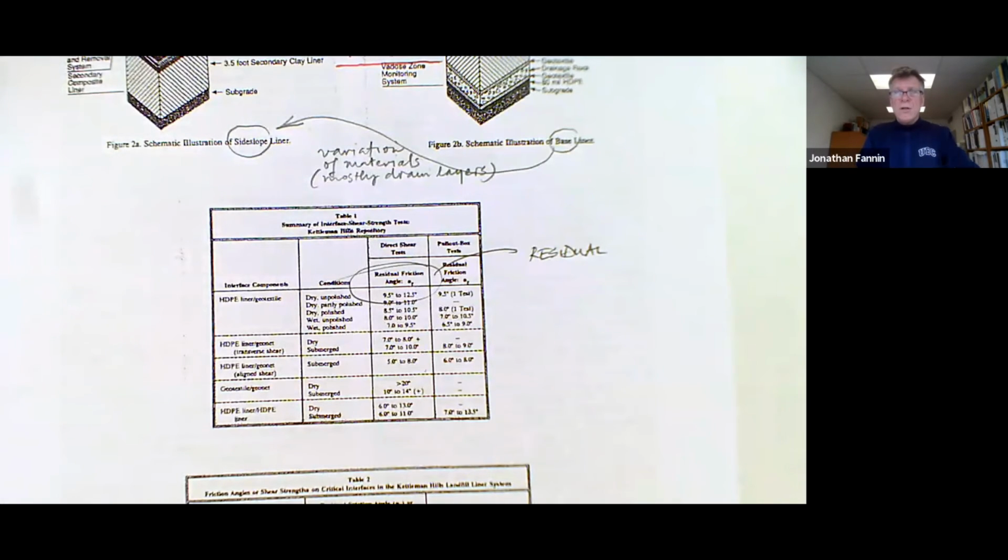And on that job at Curzio Dam, one of our challenges was to choose a geomembrane that was going to be, for example, compatible with the water quality issues. We ended up choosing a fish grade PVC, and then another challenge was the very short construction window and being able to get in and seam and join and get out in the narrow construction window between the snow melt, typically full melt in July, and early onset of winter snowfall in the September-October period. So a very, very tight construction window.